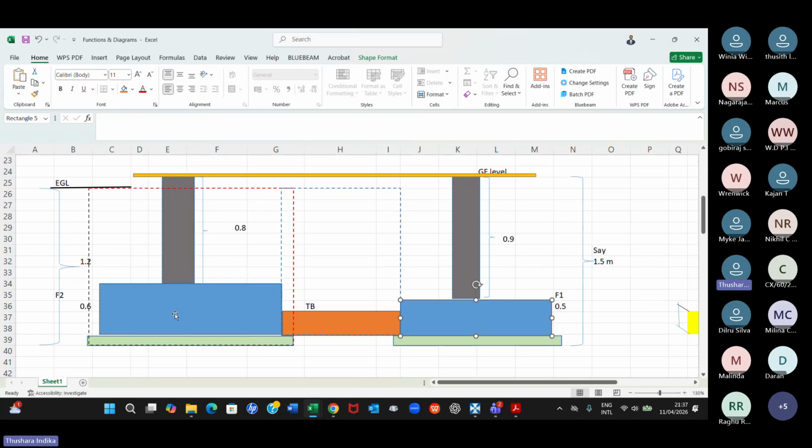We have taken the footing surface, side and top, and then we have to take this edge, other than at the intersection points. So forget about the intersection points. Let's assume this is a measure and pay contract and you want to get an estimated figure. Otherwise, you have to deduct these intersections.